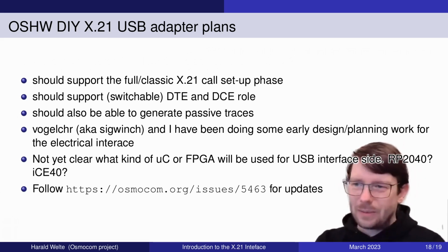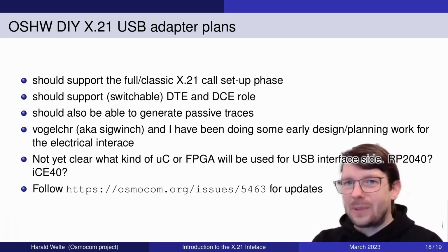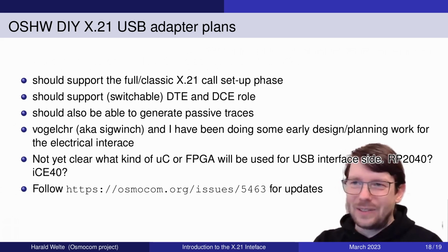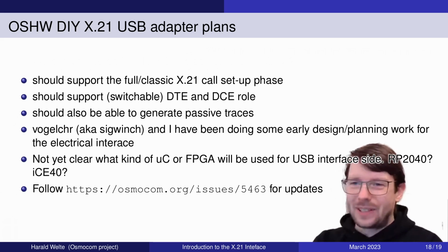Microcontroller software-based approach, for example, with an RP2040, is certainly a more accessible approach to people mainly doing software development. But if everything else fails, we might need to turn to an FPGA. But I think the requirements are, especially at the interface speeds that we're talking about, up to 64K in those networks, we should certainly be able to do that all in software from a microcontroller, in the worst case with bit banging, but the PIO units of the RP2040 should help us there.